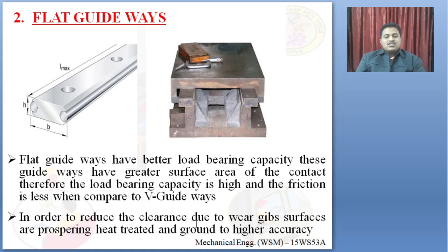In order to reduce the clearance due to wear, the gib surfaces are properly heat treated and ground to a very high accuracy. Usually we use gib keys in order to maintain the required clearance between these surfaces.